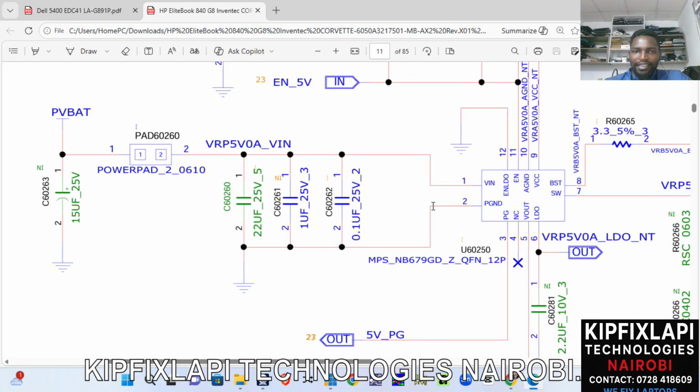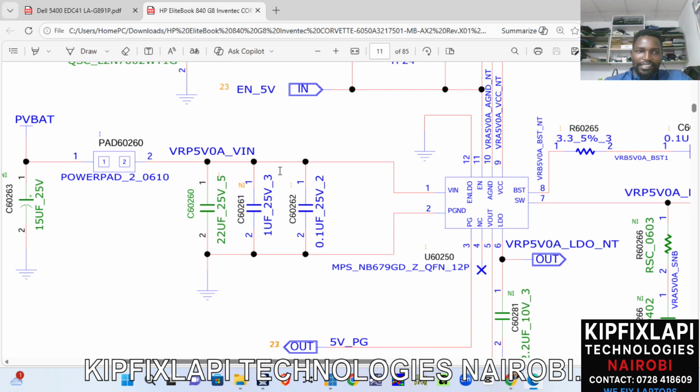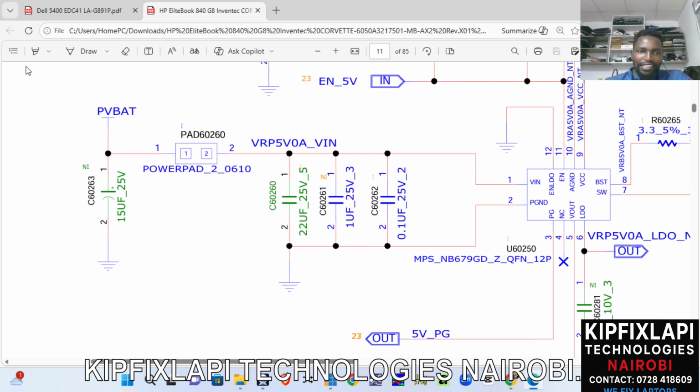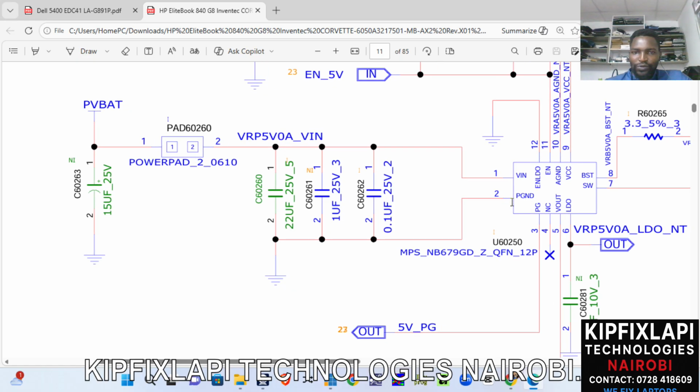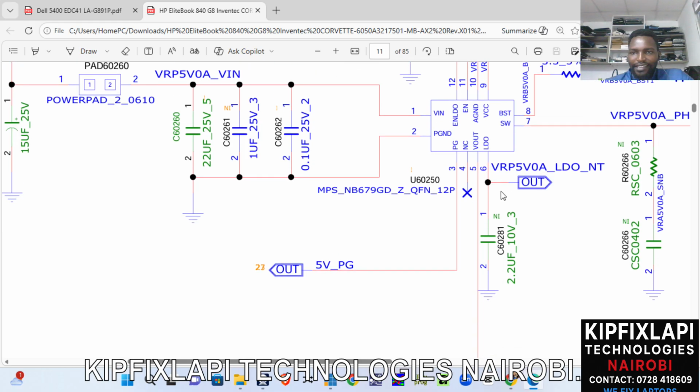Yes, this is another IC. This other IC also has pin number 1, voltage in, and this voltage in is coming from the PV battery. Then it goes into that IC. Here, pin number 2 is the ground, and it is indicated that we have other signal lines. V out means the voltage out. Since we had V in, voltage in, this is V out. Then you have the LDO line, going this way, then going out.